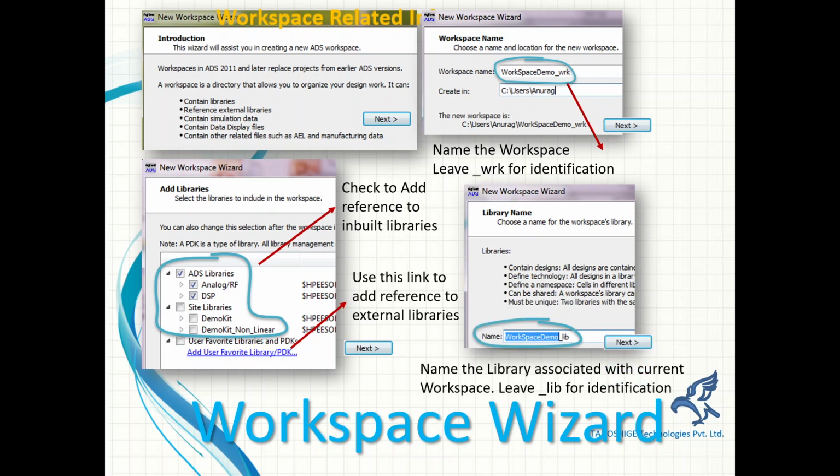Okay, so basically you provide a workspace a name, and then underscore work, WRK, is basically what tells ADS that this is an ADS project workspace. You shouldn't remove underscore WRK, and whatever name you want to give should not have white space characters other than underscore, and should not start with a number or a white space character, or any special character, right? Like dollar sign or hash. It should not have spaces, because it may work with the spaces, but at some point it may break.